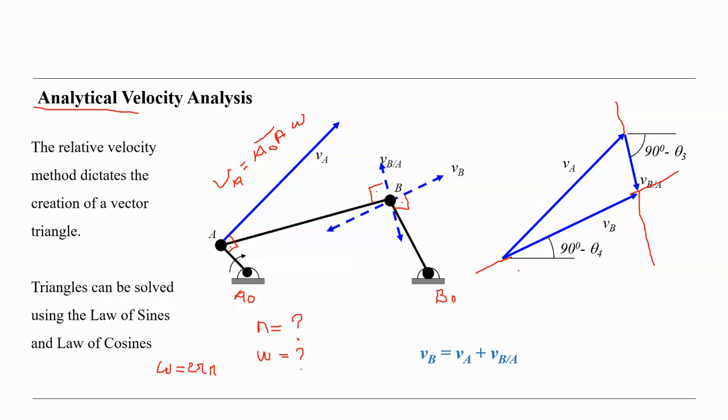we can find the magnitude. We know the direction, and we can calculate. We can also find the magnitude here, using the scale for the VA. But if you know the angles shown here, using the sine law or cosine law, we can also calculate the unknowns.